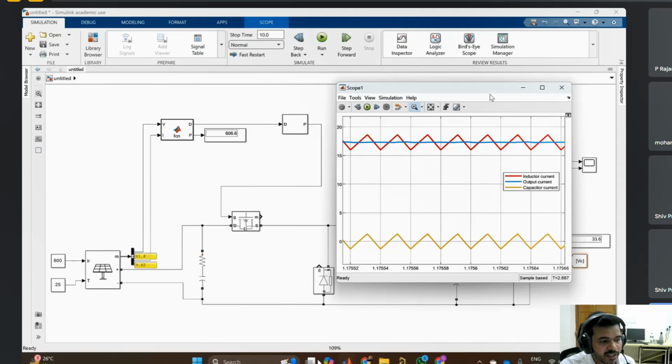Inductor and capacitor are not operated in DC; they give an open circuit or short circuit. If you want to operate the inductor and capacitor in a DC converter, then you should follow flux balance and charge balance. Flux balance for an inductor and charge balance for a capacitor.